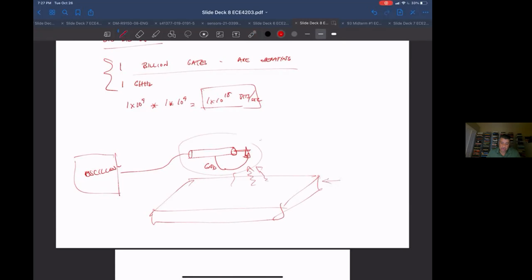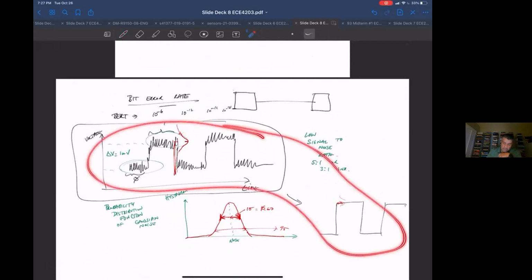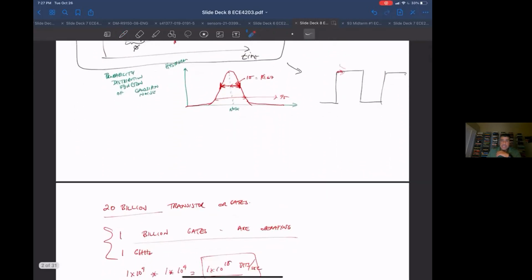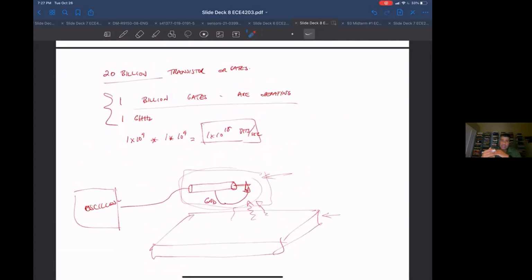And you'll see some horrendous tens, maybe 100 millivolts of noise just emanating everywhere, just from electromagnetic interference. And so anyway, the upshot is the actual noise situation in a real world environment for digital circuits is much, much worse than this broadband noise thing that we're talking about. So all that means is you need a very high noise margin. Otherwise, you're going to have errors in your calculation or communication in your digital circuit. And usually you have not built in any protection in your system about that.